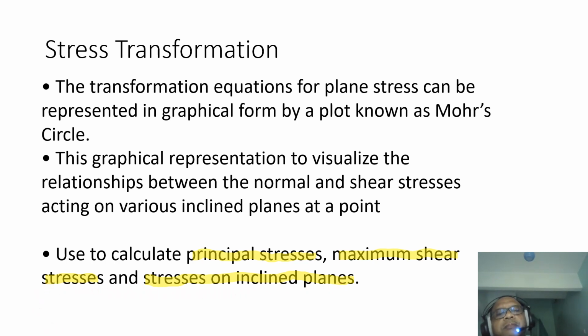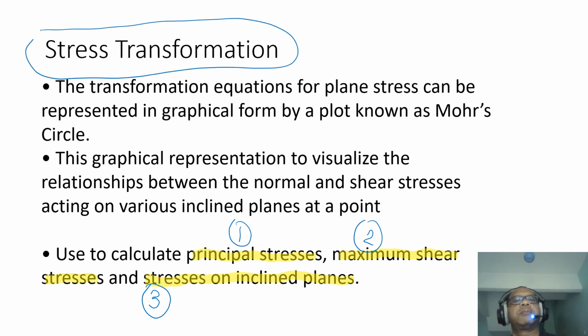Most of the time, we are interested in finding the principal stresses and the maximum shear stress, and sometimes we also want to find the stresses at other angles or orientations. That's what stress transformation is all about. When we say transformation, we want to find the normal and shear stress acting on various inclined planes at a point.